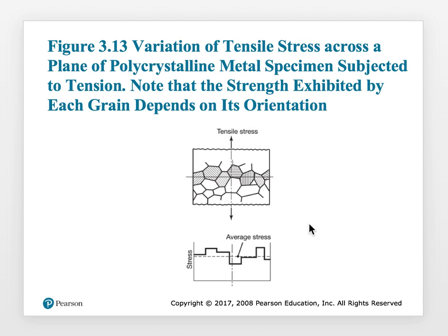So how do you get an average number? Over this entire block of atoms and entire sets of grains of atoms, you have an average stress that is required in order to move those sets of atoms. So that's what you are testing by doing the tensile testing.